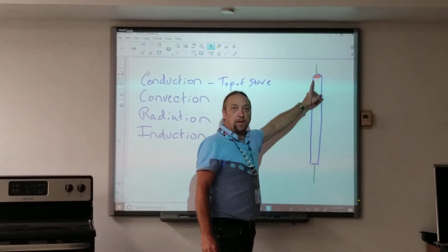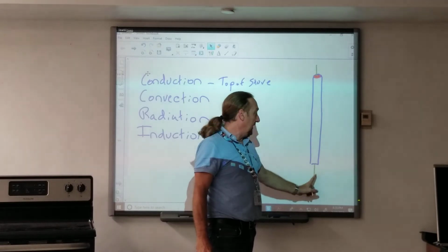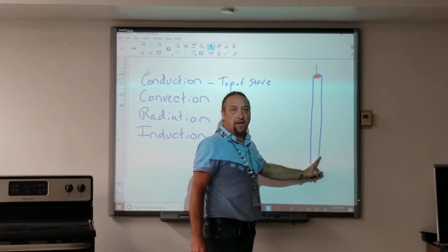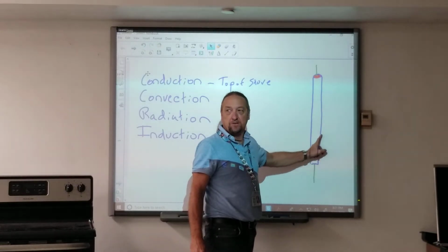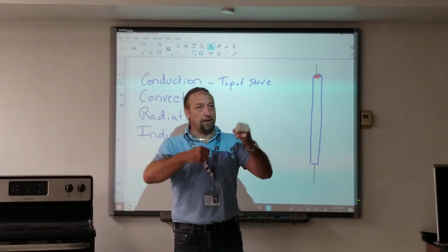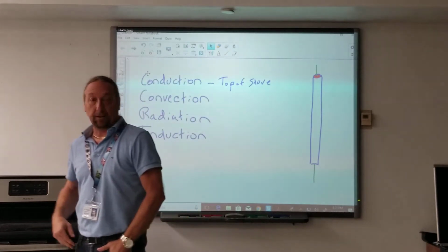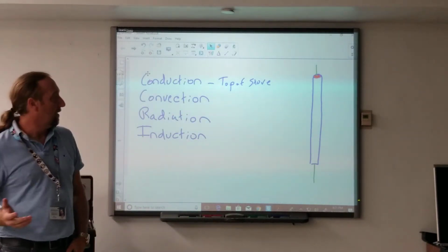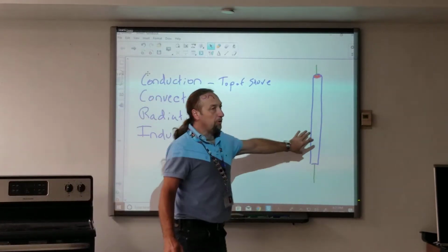And what happened is when they formed this, either it was too close to the edge here or there, eventually the heat broke down the insulation and then it touched the metal and then it blew up like an electrical arc. It blew holes through the element. Now the element's no good. But this is a perfectly round tube.